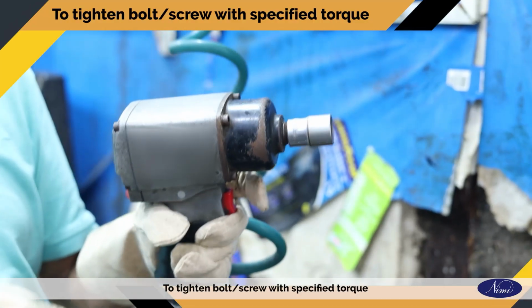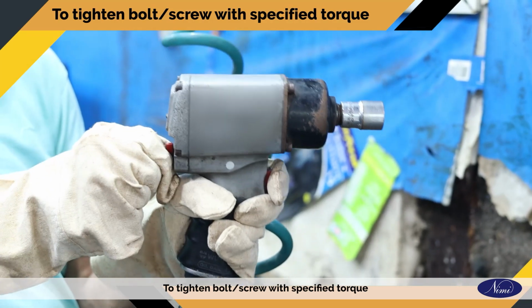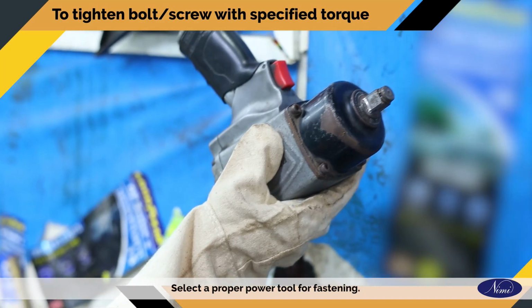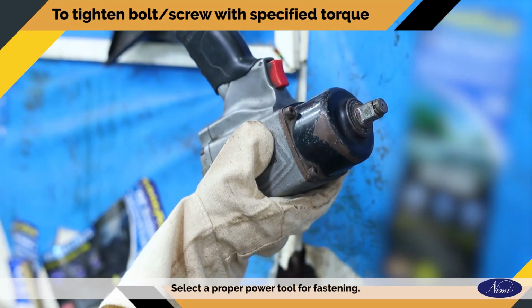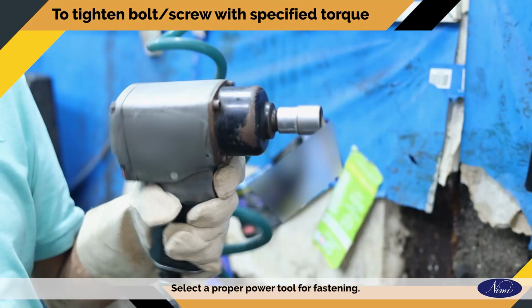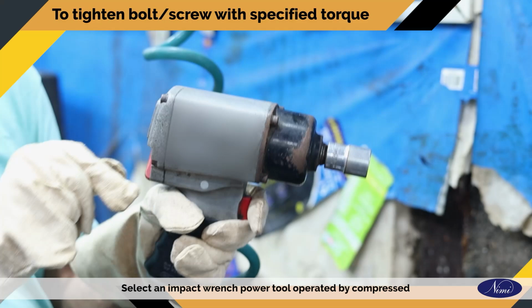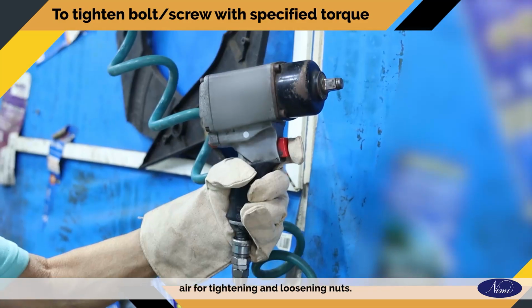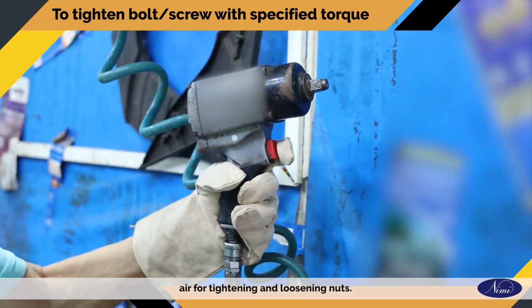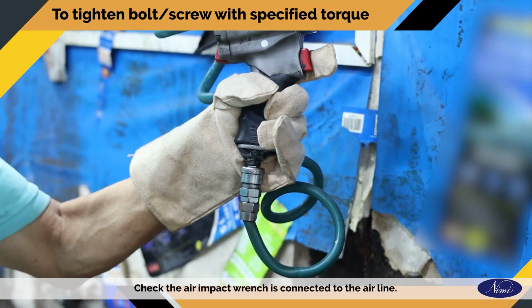To tighten bolt or screw with specified torque. Select a proper power tool for fastening. Select an impact wrench power tool operated by compressed air for tightening and loosening nuts. Check the air impact wrench is connected to the air line.